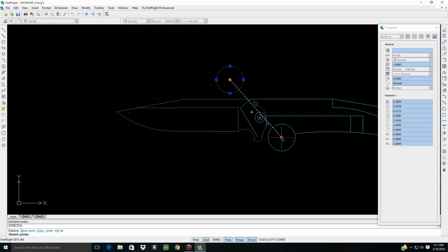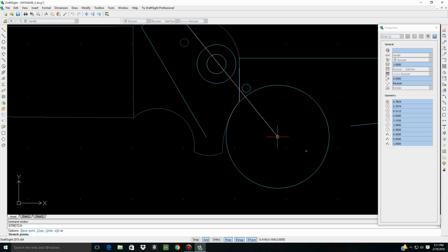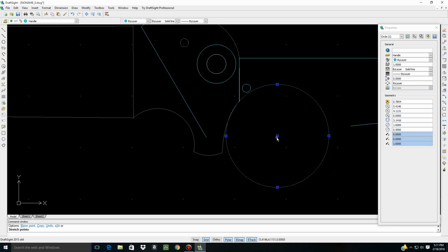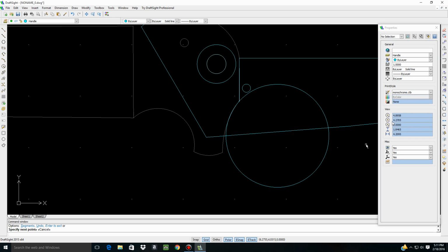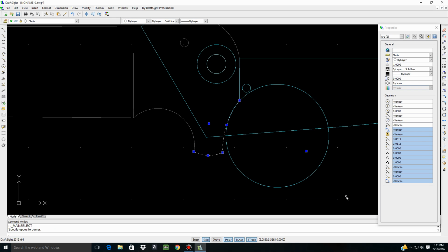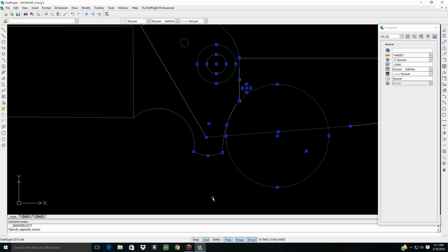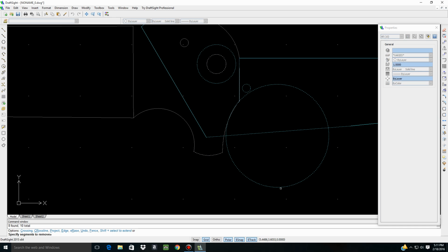You know what? We're going to have to go just a little bit bigger. Actually, right there looks pretty good with our 1-inch circle. Let's bring it down just a little bit. Maybe right there. Okay. We're going to just connect the line from here to here and get rid of all the stuff we don't need. So hit escape to get rid of that line. Highlight all of this. Oh, the whole circle. There we go. Trim out the bottom.